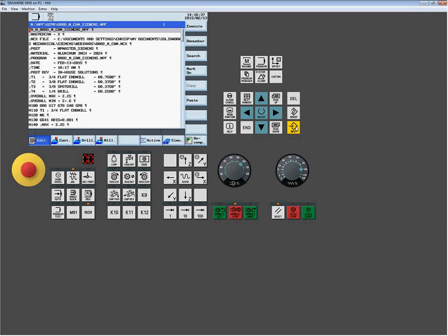It's a very traditional G-structured program coming out of a CAD/CAM system. You see a bunch of notes here at the top. So these are certainly very handy. So I have some tool notes, a few different tools defined for me, as well as maybe posting time, source files, that kind of stuff. Then from there, anything with these semicolons, so semicolons are what we call comments. So anything you want to put any type of user note in the program, just simply put a semicolon. Everything after it will be ignored.